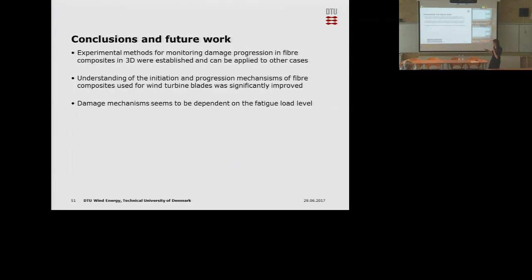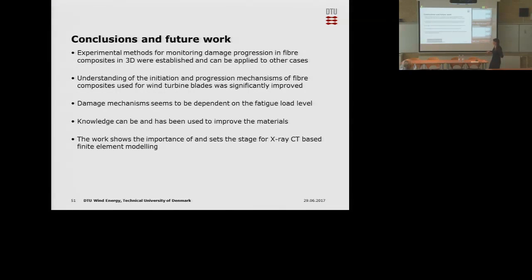It was found that the damage mechanisms depend on the fatigue load level, which is, I think, important to consider in the future, because we might actually be testing something which is not the same as what occurs in the real structure. All this knowledge can also be used to improve the material. Finally, this work shows the importance of, and sets the stage for, X-ray CT-based finite element modeling, where you can include the real fiber bundle structure and the real fiber structure in your models.